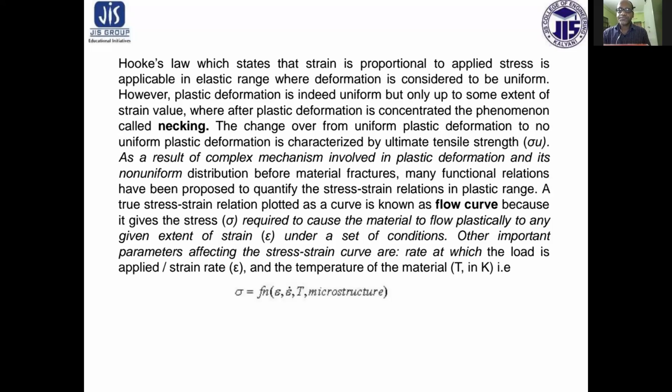However, plastic deformation is indeed uniform, but only up to some extent of strain value. Thereafter, plastic deformation is concentrated, a phenomenon called necking. The changeover from uniform plastic deformation to non-uniform plastic deformation is characterized by the ultimate tensile strength.